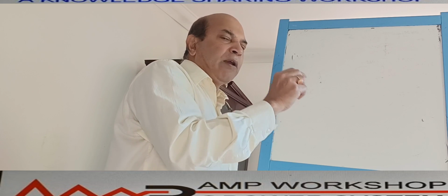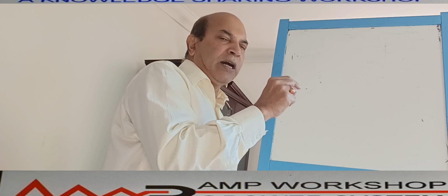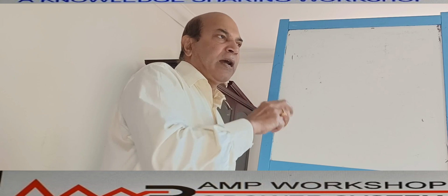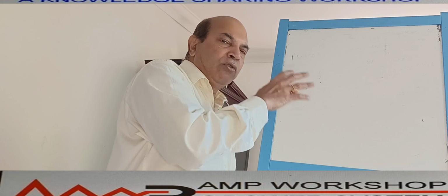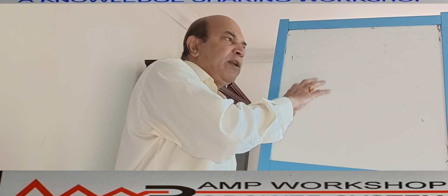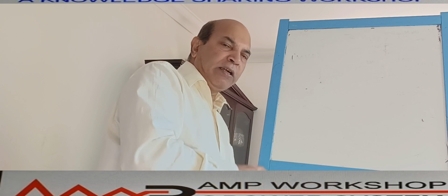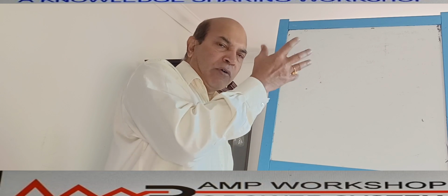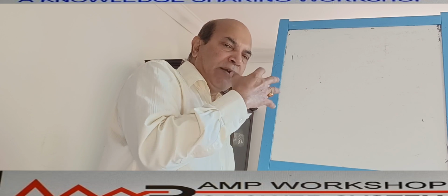Then you have to identify which bus you want to calculate the fault current. Identify that bus. Then you see who is feeding the fault current. Identify all the feeding items, those feeding in parallel. Those circuit equivalent impedances you put in parallel path. Calculate the equivalent impedance. From the equivalent impedance, now we go back to our basic assumption. We consider base MVA 1.